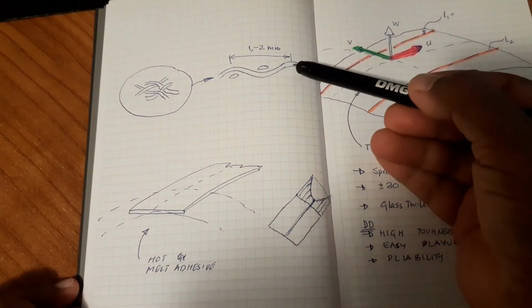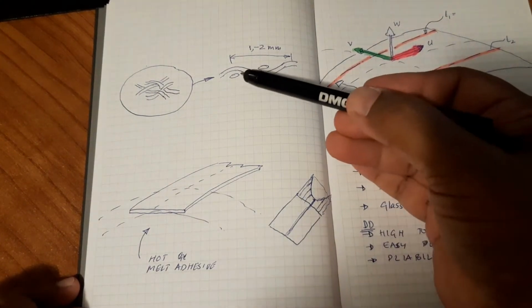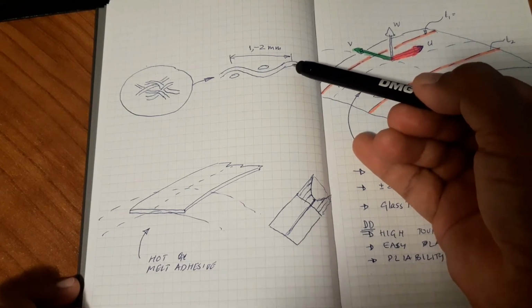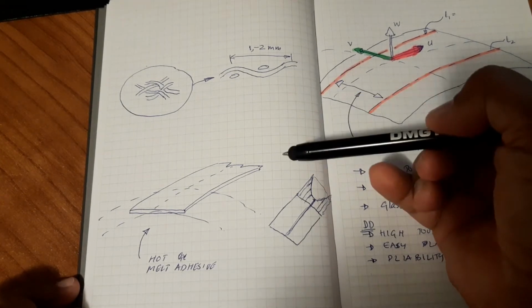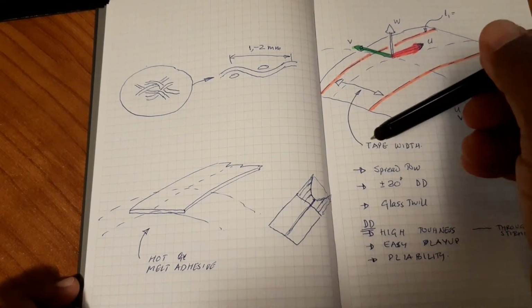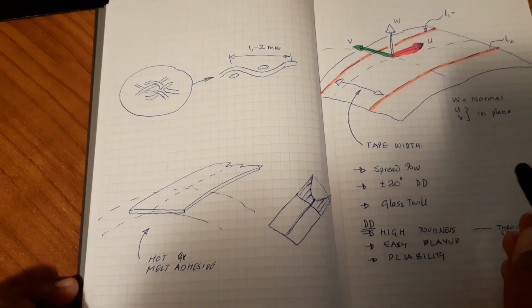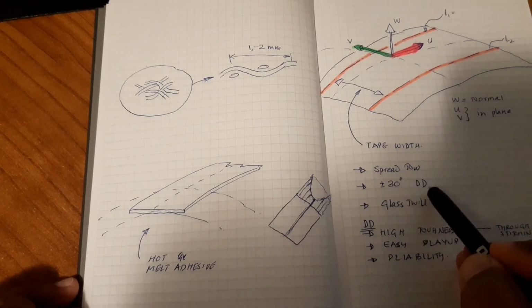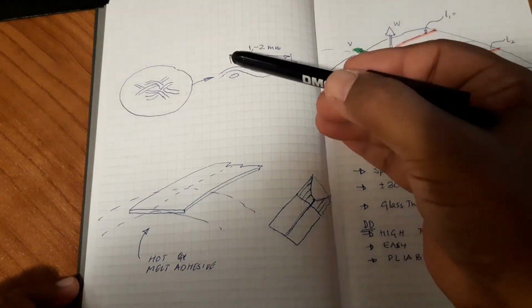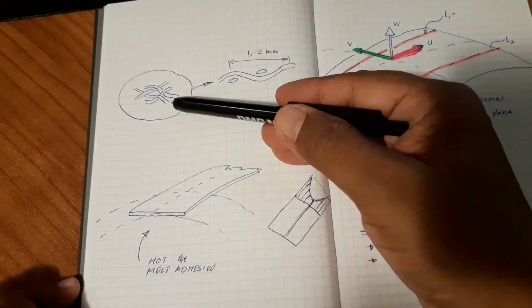Now, as far as cloth is concerned, cloth will lay up very beautifully on this without any problems. But the cloth has a big problem, and the problem is that its compressive strength and compressive stiffness is abysmal compared to structural components made from NCF, which is non-crimp fabric. And when we talk about DD, we are talking about non-crimp fabric. And that abysmal strength actually comes from the fact that cloth is woven like this.